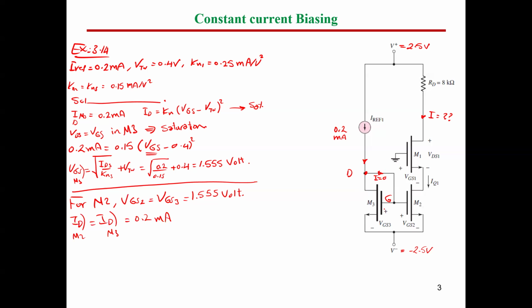It will absorb current just in the transient period in the beginning. And at steady state, once the MOSFET is turned on, no current will flow anymore in the gate. Okay, because by the end it's going to be a capacitor, and a capacitor at steady state will not allow a DC current to flow. So this is a feature of any MOSFET.